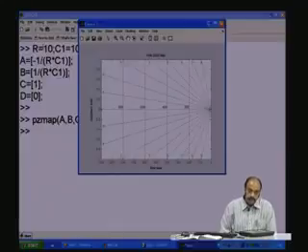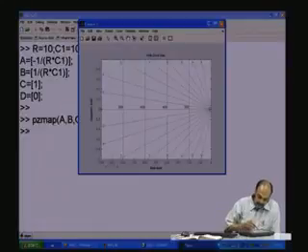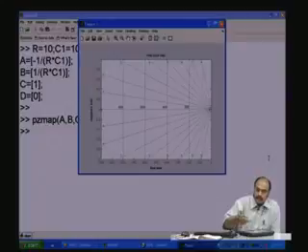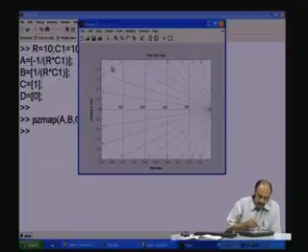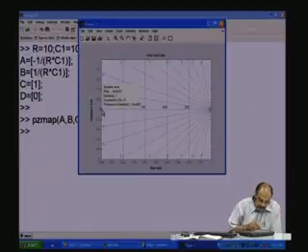So, you see the S plane, and here like I was saying, this is 0 and all going negative, which means only the left of the S plane is shown, the right of the S plane is not shown here, because there is nothing there to show, there are no poles there. So, all the poles are located of course here in this left half of the S plane, and that is at this point. Are you able to see this blue X mark here? That is the location of the pole for this circuit.